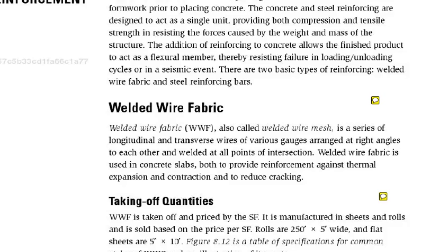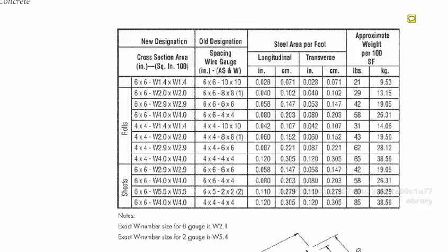There's equivalence between welded wire fabric and reinforcing bars that you can transfer, but for you as a contractor, you're going to put down what the designer specified. You may in some cases do some value engineering, but you can't arbitrarily change reinforcing bar to welded wire fabric because you think it's best, or you have some sitting in the back 40 you want to use up. You can see this table will tell you the characteristics of the welded wire fabric, the sizes.